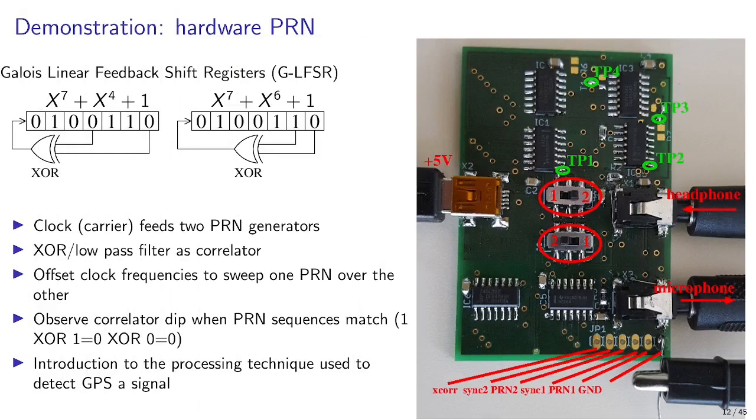If we look at the scheme that was described on the slide, we see here that, for example, we go from the least significant bit to the most significant bit, so that we have 1, 2, 4, 8, and 1, 2, 4, this is represented as hexadecimal 48. We see here 1, 2, 4, 8, 1, 2, 4, this is 2 plus 4, this is 0x60. Indeed, these two tap locations, 0x60 and 0x48, are indicated as maximum length sequences.